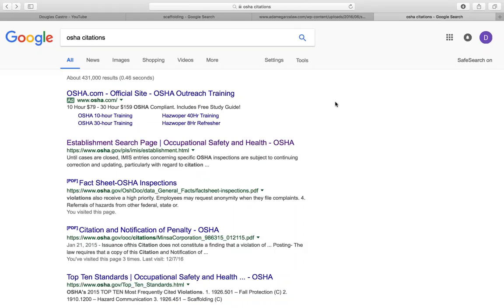Maintain a JSA as well. Okay, have fail-safe documentation. Have multiple documents, right? So you can cross-reference. Is there a means provided to identify any and all employees who are working on locked out equipment? Okay, by either the locks or the tags, right? By group. Is there a sufficient number of accident prevention signs or tags, basically telling us, hey, do not energize, right? We're in the lockout tagout process.